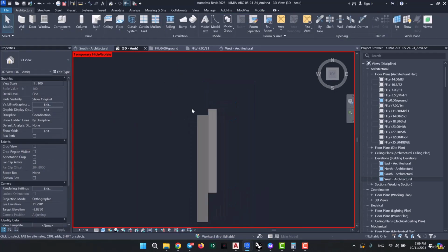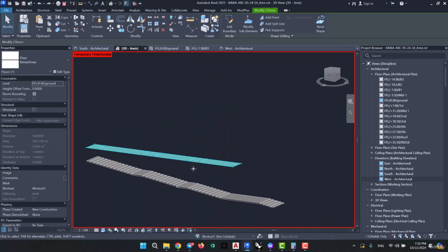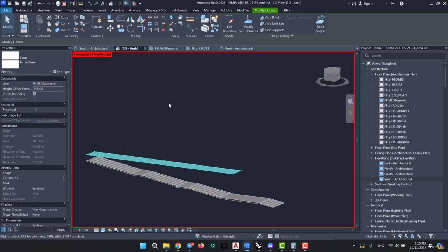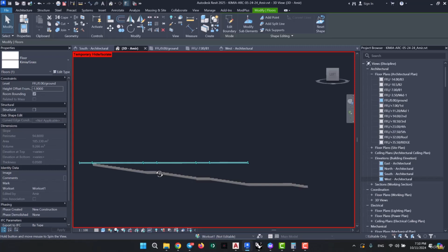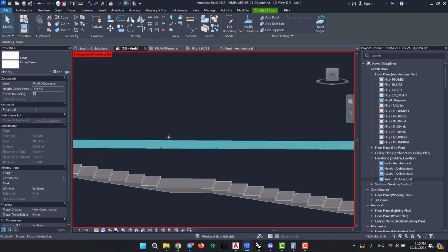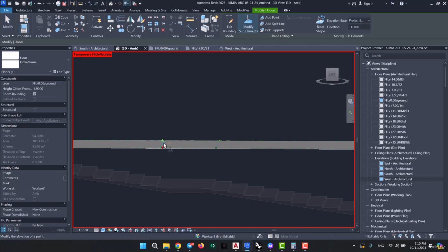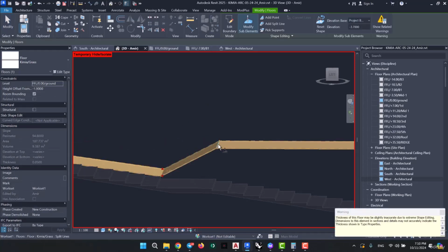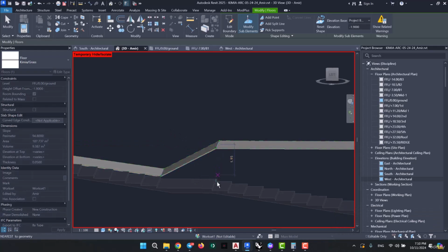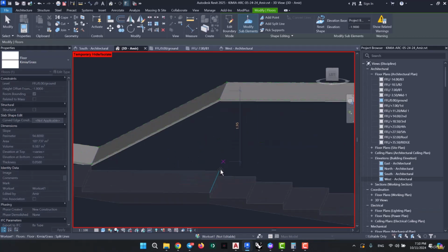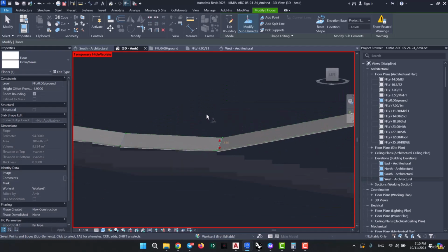Alright, so now the first thing I'm going to do is adjust its offsets. Just like the flights of stairs, if we consider the height of this garden, it should end at the same offset as the top of the stairs. So first I'm going to adjust its offset value. That's for the top, it's negative 1.90, and for the second part, I'm going to apply the slope. I could easily just select it and modify sub-elements, and then I'm going to grab it by this line and drag it downwards. After that, I'll select this one and bring it down to this edge over here, and as you can see, it's pretty easy.